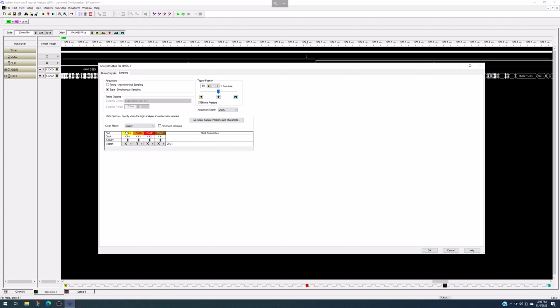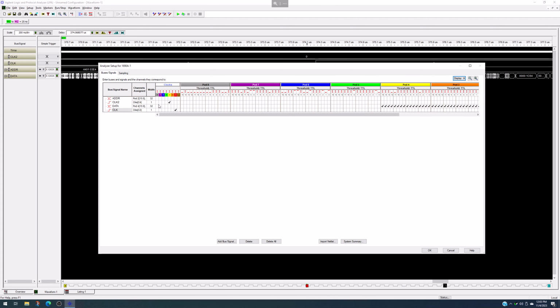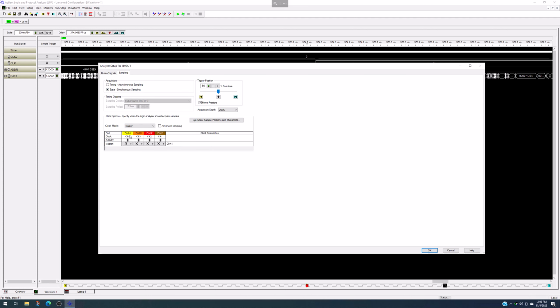So in pod 4 is where I'm bringing in clock 2, or sorry, in pod 3, I'm bringing in clock 2. Let's go double check that. No, I said pod 4. I've got this on the wrong one. Let me correct that. Both edges, don't care. Okay, so over here, I'm saying I'm grabbing clock 2 on this 4, and if it is either rising or falling, wherever those edges are, that's when I actually want to do a capture of data.